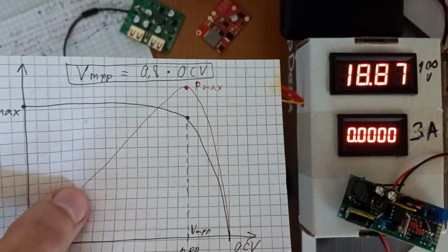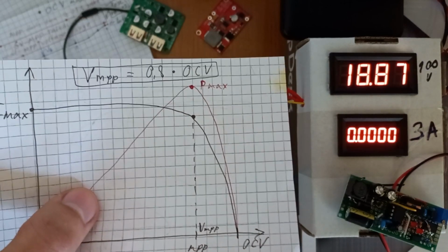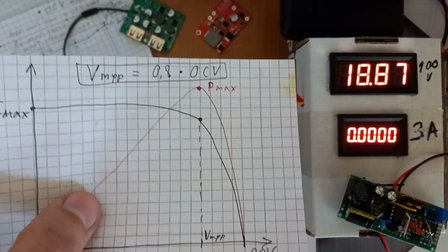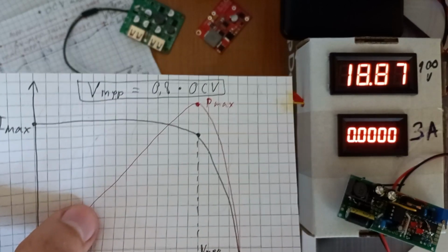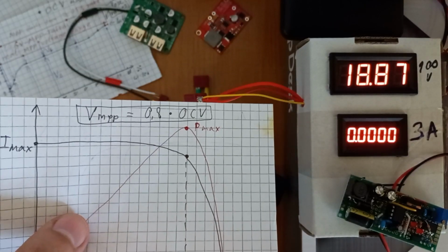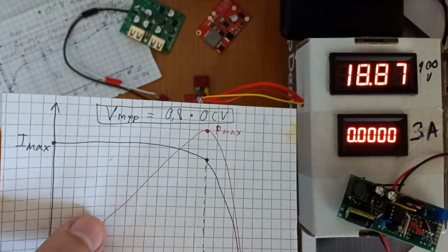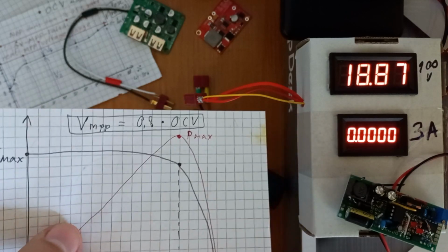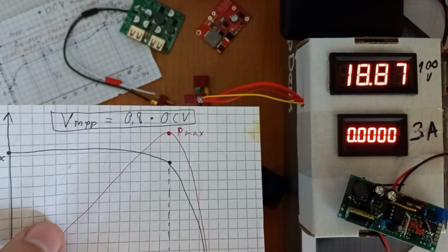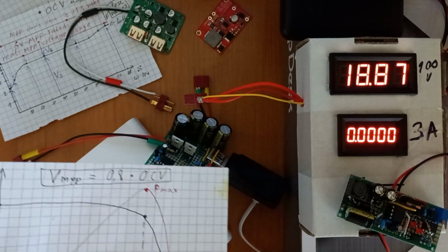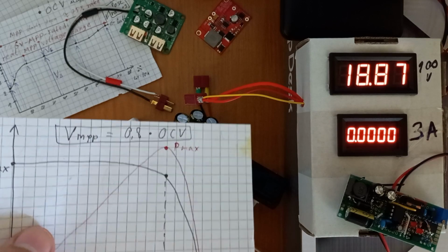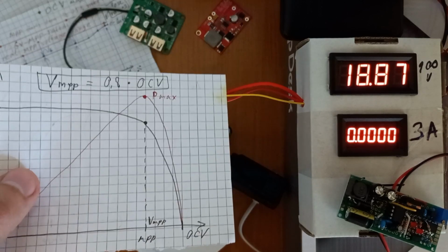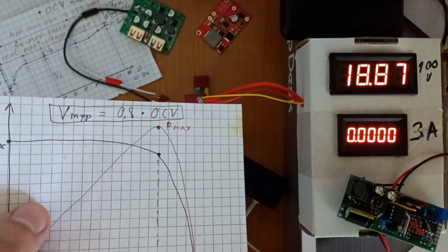If you place panel in non-optimal angle, you will receive less. If you place it behind some window, you will also get around 30 to 50% less. Now about voltage specifications. There can be confusions with voltage in product descriptions. There is often referred to system voltage, which means a voltage of a battery being charged. So it can be typically like 12 volt system, 18 volt MPP, and 22 volt OCV.